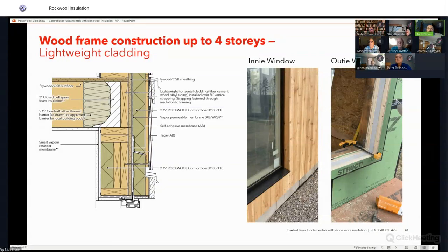However, if you didn't do something and say that was a normal house, say that's a garage attached to your normal house, because I've seen this quite a bit, where they'll just insulate it, they'll walk away because they're doing other stuff, and years later they come back to do it. Well, you certainly have a huge potential to have some mold related issues on that sheathing, because every time you turn your car on, you open your doors, whether it's the big garage door or the house door, you're letting a lot of vapor into the assembly. So when it gets colder, it's going to start condensing very quickly and potentially causing some issues.